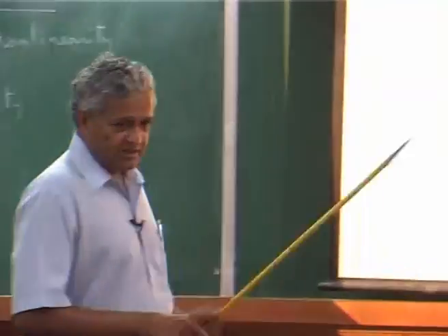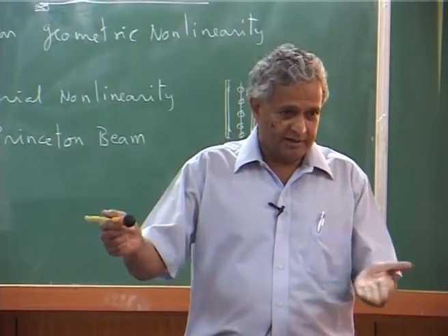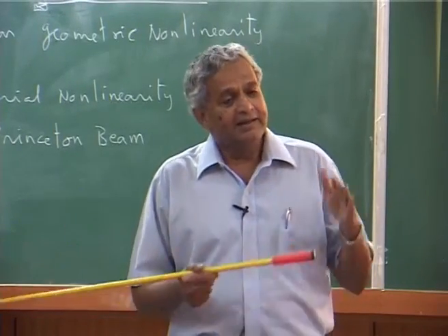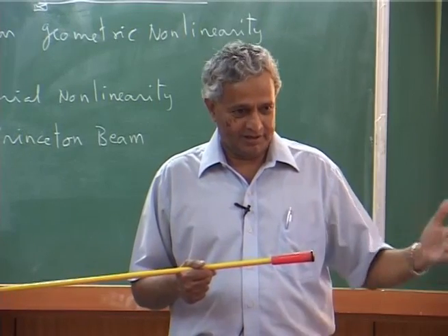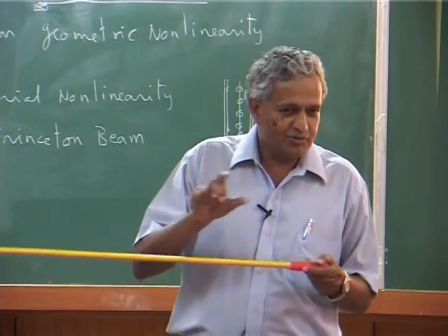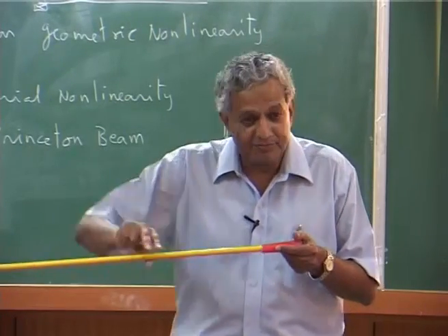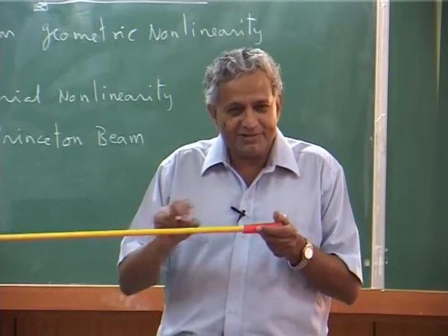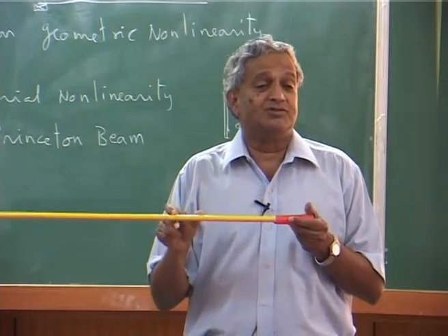But most of the hingeless blades, because I know the ALH blade, the pitch bearing is inboard, okay, and there is no flap hinge per se, but there is an equivalent flap hinge, where some soft stiffness drops at some section and that becomes kind of a hinge.